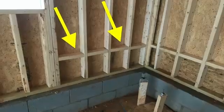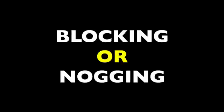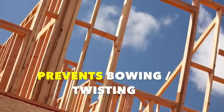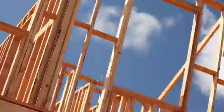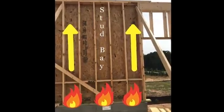You'll also see little horizontal sections of wood in framed walls. These pieces are known as blocking, or in some countries, nogging. Blocking serves many different purposes. In tall walls, it prevents studs from bowing or twisting. In some cases, it provides a fire block, which prevents fire from traveling up the stud bay like a flue. This slows the fire down so it can't leap between floors.